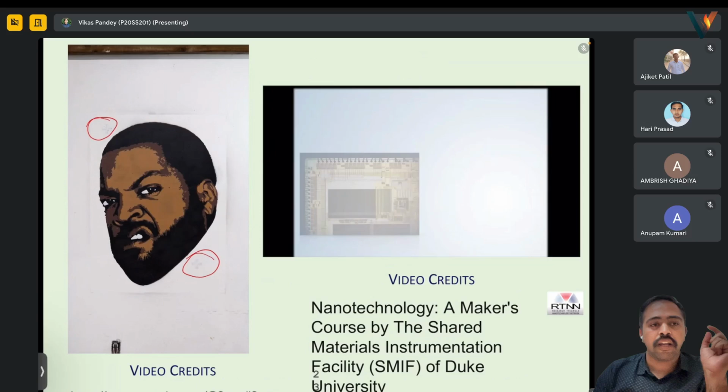Then you use a photomask. This is a simple assembly. Talking in terms of lithography, it is a simple soda lime glass with patterns made using a thin layer of chromium or tungsten. We have the desired pattern, and we place it over our wafer and expose it. So light will fall only on the areas that are not covered.